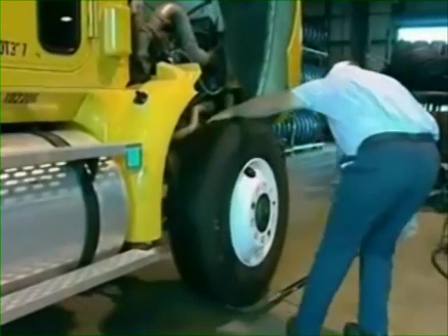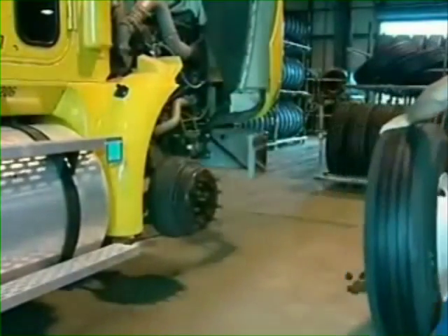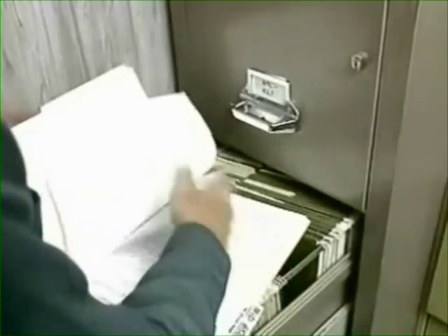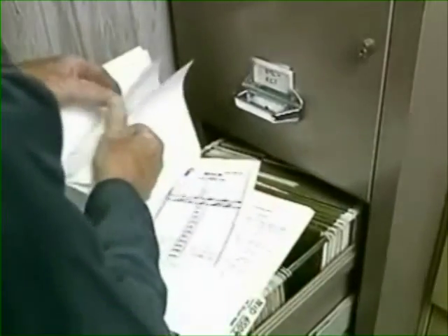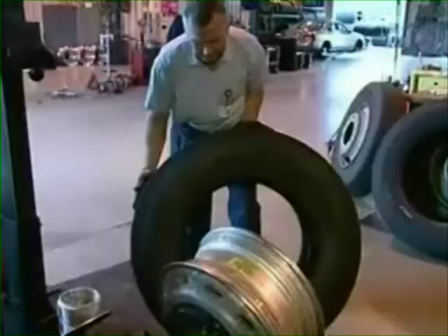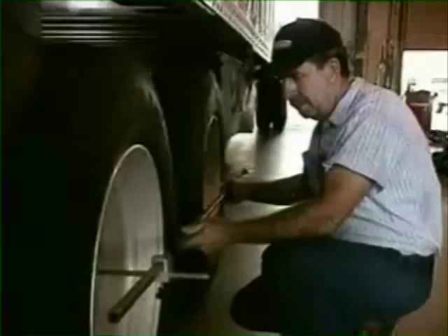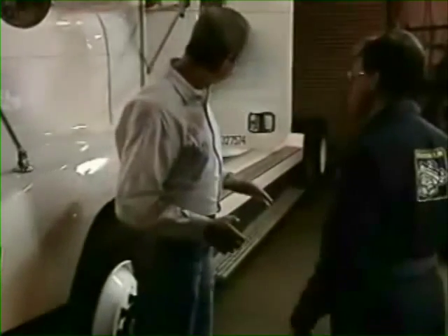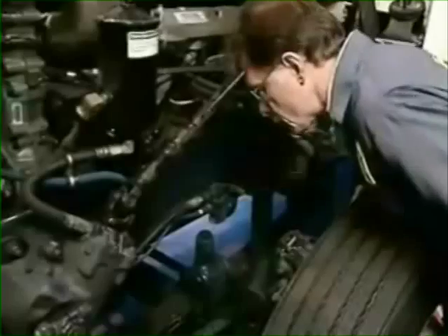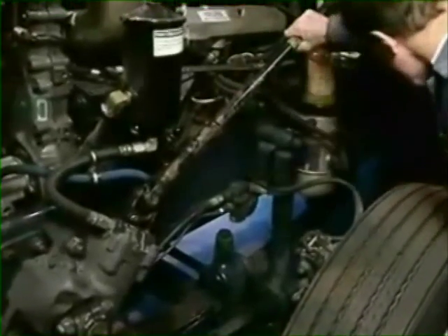If the driver indicated the vibration began just after a service, check the vehicle maintenance history to see what was performed and how it could influence the vibration. For example, has the vehicle recently been given new tires and wheels, an alignment, or replaced components such as tie rods, tie rod ends, shocks, etc.? After the interview and review of the maintenance file, it may be possible to determine the source of the vibration. If more information is needed, then inspect the vehicle.